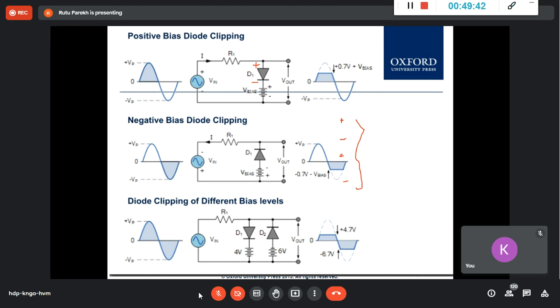But if this is 2 volt and this is 3 volt, but the terminals are minus and plus here, and this is plus and minus, and then the minus terminals are connected, right? Then it will be minus 1 volt resultant. You know that. Okay. So when you are considering, as I said, let's say this is some bias voltage and this is a 0.7 drop. Then instead of just the 0.7 drop, you will add that bias voltage also. If this is 1 volt, then this is 1.7.